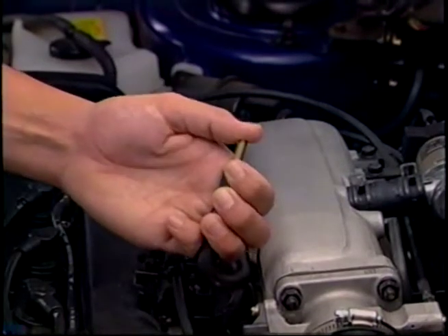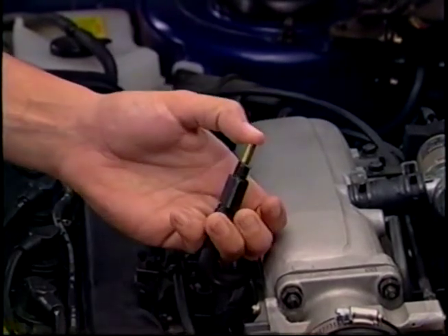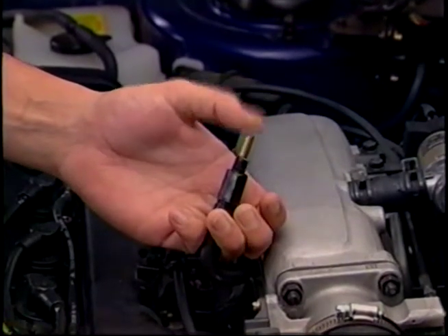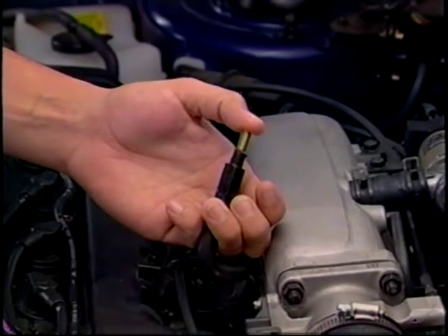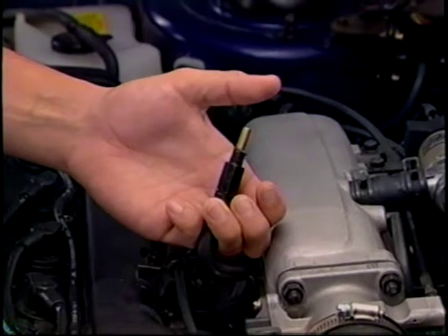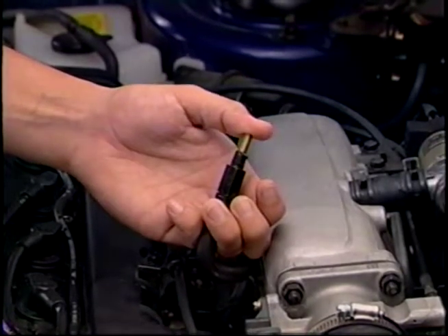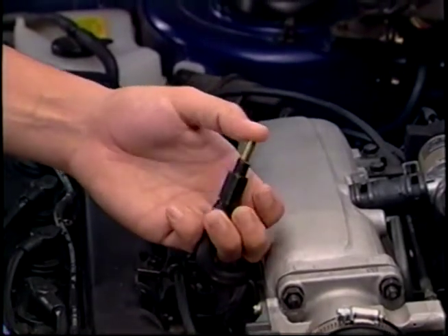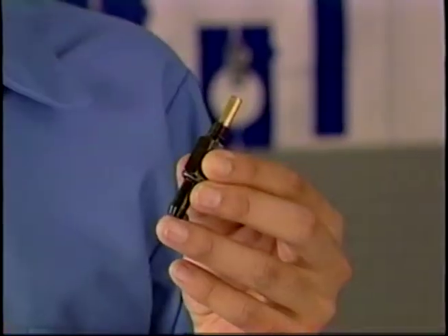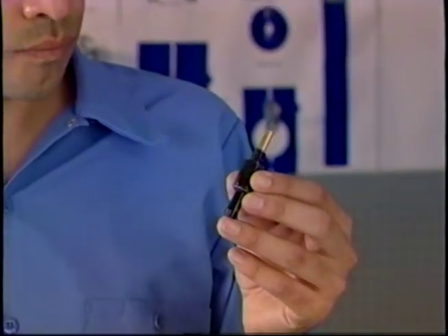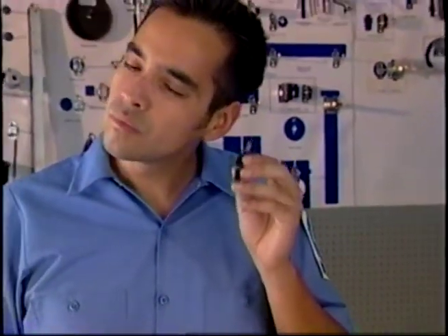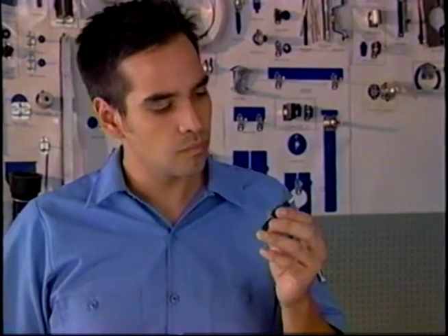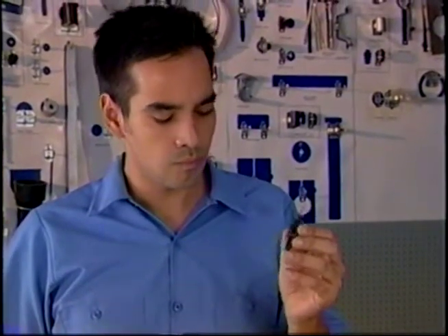Lastly, don't overlook the PCV valve. Check the PCV system by placing your thumb over the PCV valve inlet with the engine at idle. If you feel little or no vacuum, check the PCV valve, hoses, and fittings for restrictions or leaks. Gently shake the PCV valve to make sure that it is not stuck open or closed. A PCV that is stuck closed will result in excessive crankcase pressure and excessive blow-by gases into the combustion chamber.